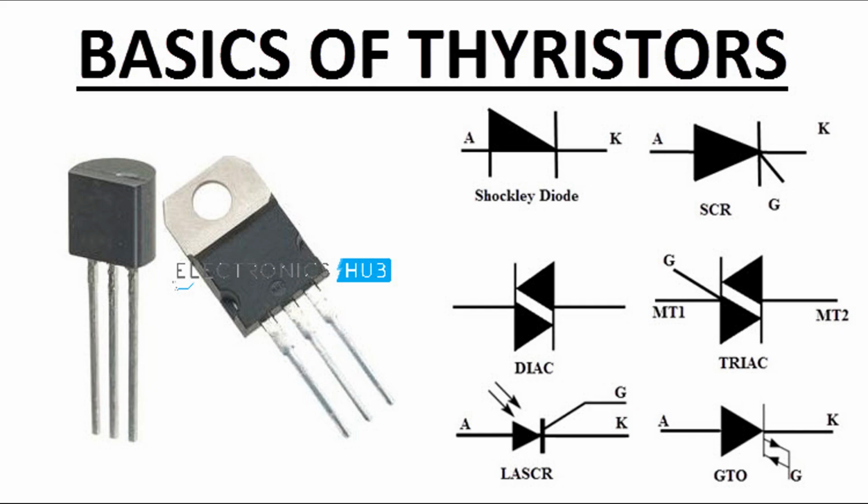Turn on pulse. A positive pulse is applied to G1, turning on the SCS and allowing current to flow. Pulse output. The SCS conducts and provides an output pulse. Turn off pulse. A positive pulse is applied to G2, turning off the SCS and stopping the current flow. Repeat. The cycle can be repeated to generate a series of pulses.